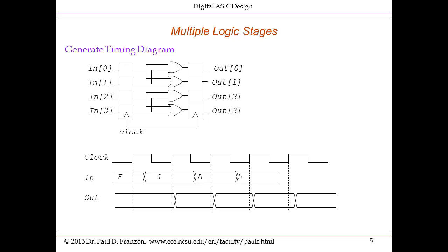So simultaneously, throughout the whole logic design, on each rising edge of the clock, all the register outputs become equal to the register inputs. And the idea is before the next rising edge of the clock, all the internal logic has re-evaluated to present the next values of the inputs to the flip-flops to be resampled. I think it'd be useful to you to actually pause this recording and see if you can produce this timing diagram based on your memory of how synchronous logic circuits work.